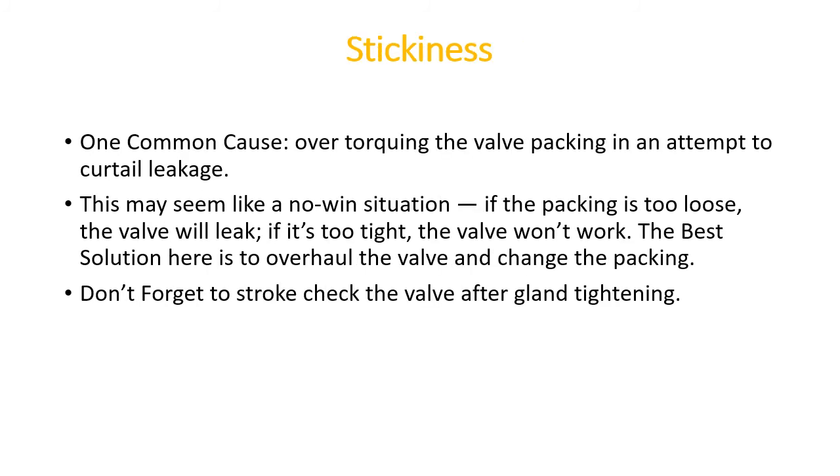Another problem is stickiness. One of the common causes of stickiness is over torquing of the valve packing in an attempt to curtail the leakage. Normally, if there is a gland leakage, we tighten the glands of the valve, but in an attempt to curtail the leakage, the packing friction increases, and sometimes the valve stem does not move.